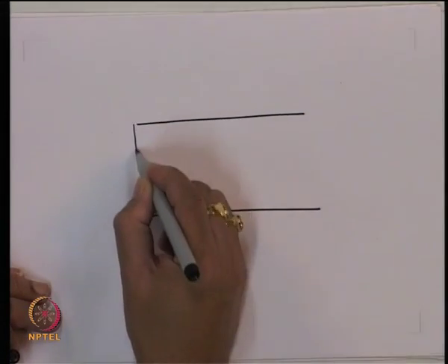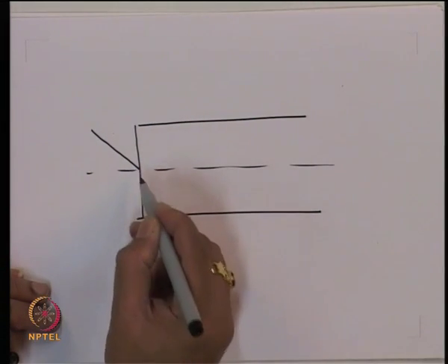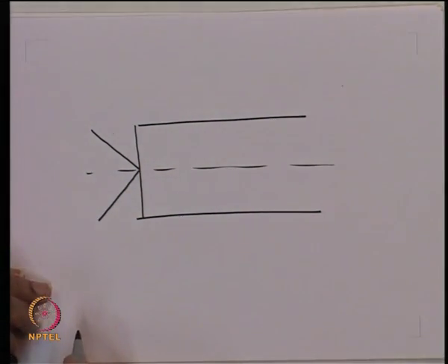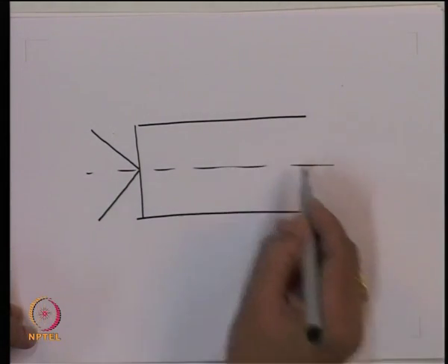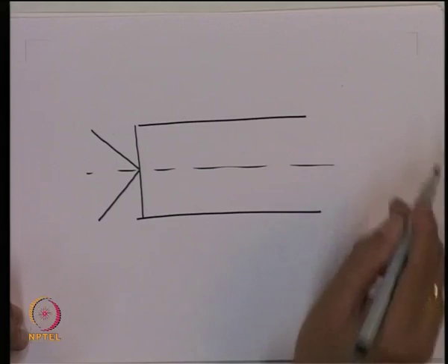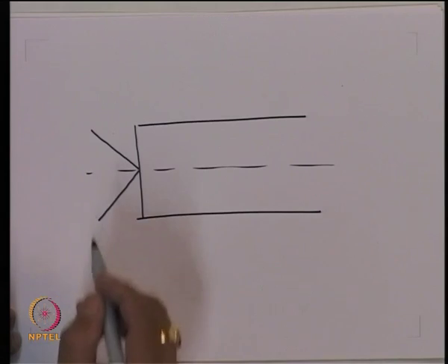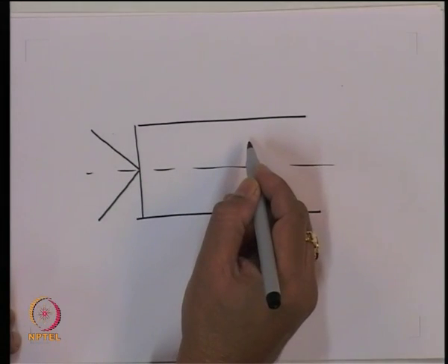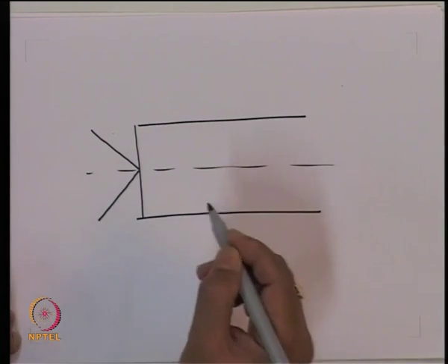So, we have said that if we consider an optical fiber like this, this is the numerical aperture cone. Earlier, when the phase condition was not needed, any ray lying within this cone would have had total internal reflection and would have propagated through this core. However, now what we are saying is that only at certain angles the ray can get inside the structure, and at any other angle the ray cannot propagate inside the structure.